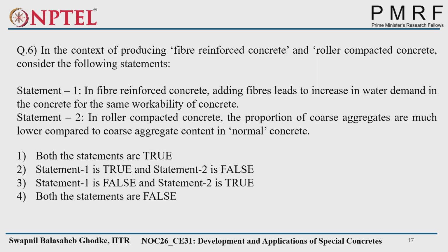So the next question is, in the context of producing fiber reinforced concrete and roller compacted concrete, consider the following statements. Statement 1 indicates that in fiber reinforced concrete, adding fibers leads to an increase in water demand in the concrete for the same workability. And statement 2, in roller compacted concrete, the proportion of coarse aggregate is much higher compared to the coarse aggregate content in normal concrete.